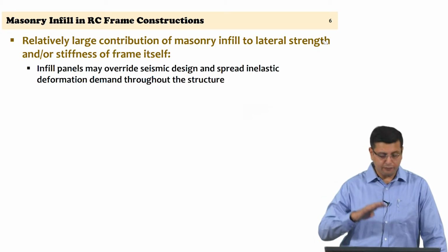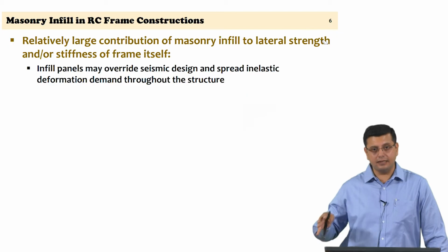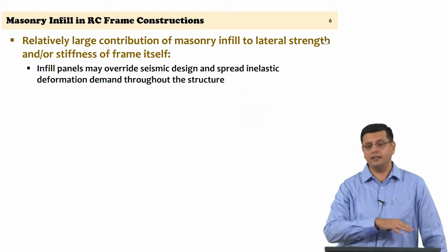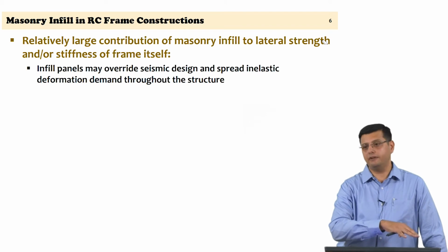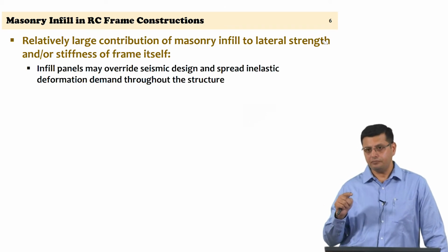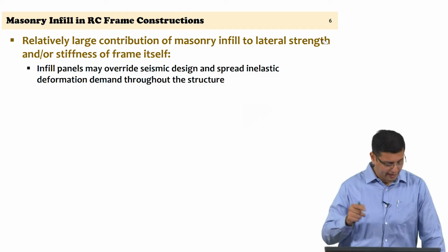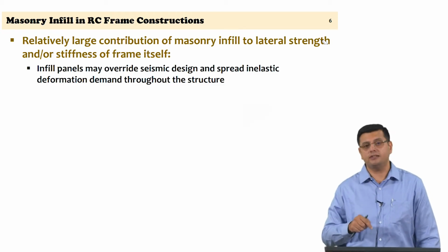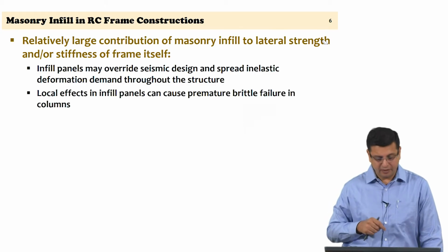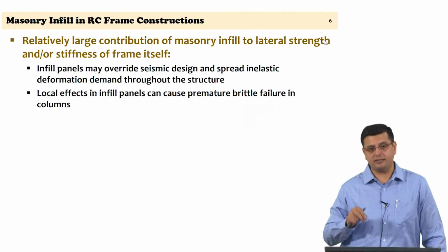So, even if seismic design were to be considered in a moment resisting frame, if the interaction is not considered and if you have strong infill panels, the problem is the demand will increase because the stiffnesses are changing, and it can cause inelasticity to spread in the moment resisting frame. So, these local effects can occur.